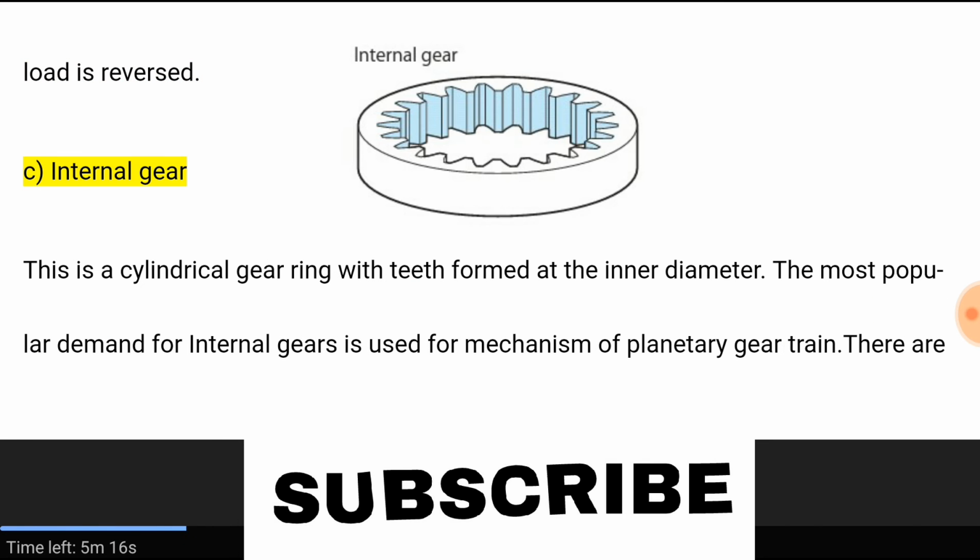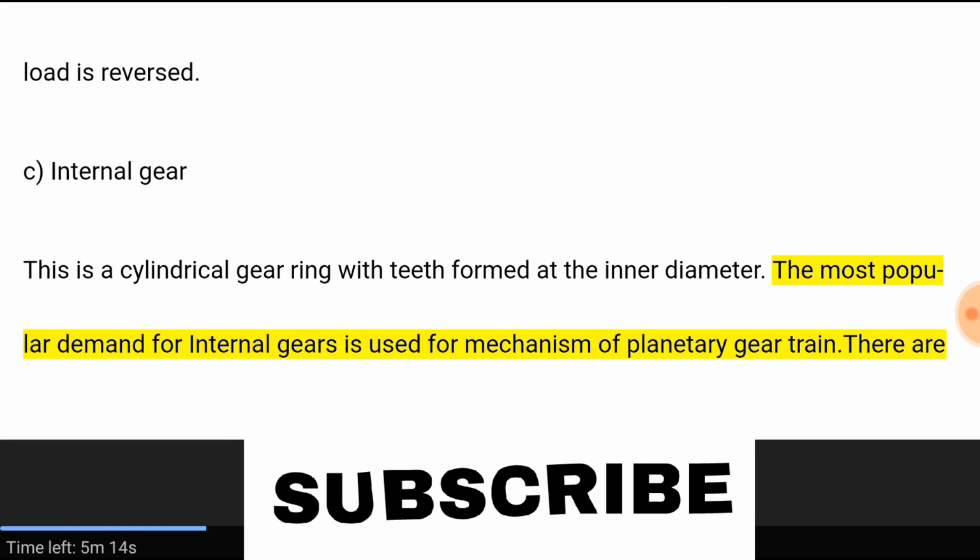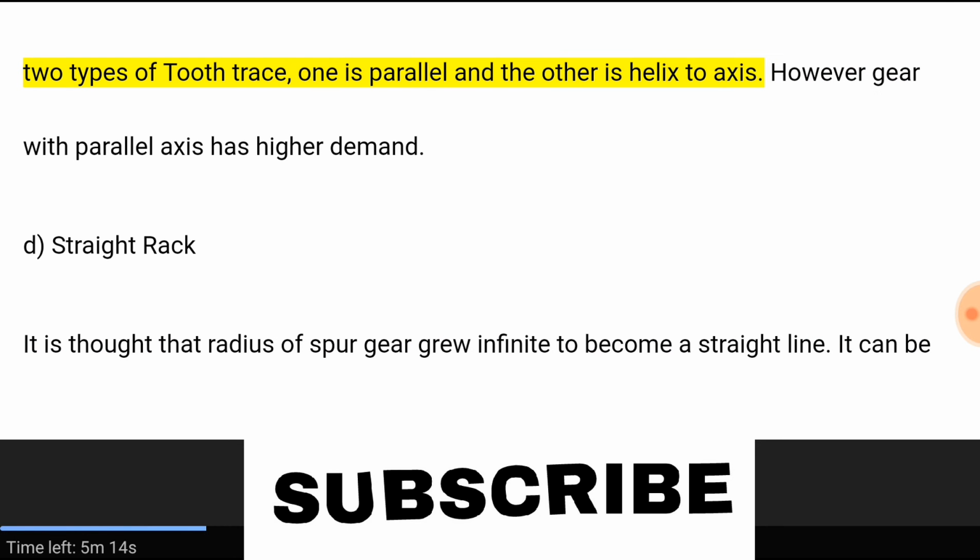C. Internal gear. This is a cylindrical gear ring with teeth formed at the inner diameter. The most popular demand for internal gears is for the mechanism of planetary gear trains. There are two types of tooth trace, one is parallel and the other is helix to axis. However, gear with parallel axis has higher demand.